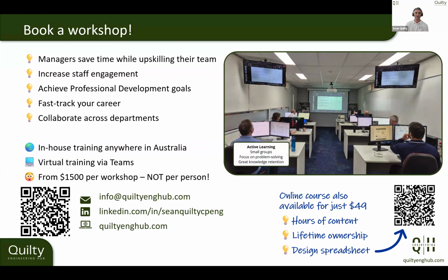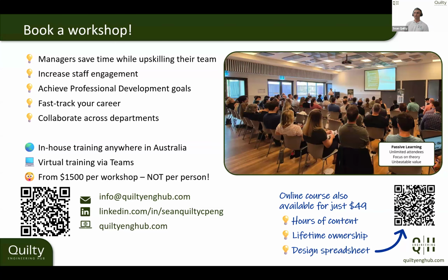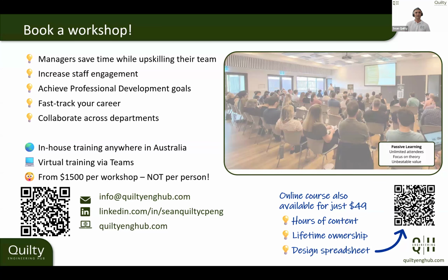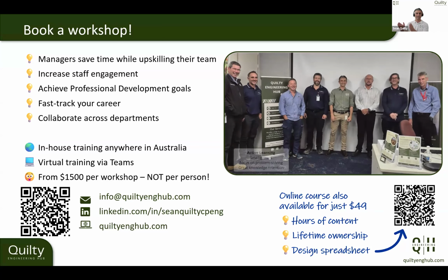It's a summation of those different slices, if you like. There's two different methods. I won't go into great detail now, but when you're looking at composite methods, you can calculate a composite Manning's roughness value and use the whole area. Or you can do this slice technique where you cut them into different sections.